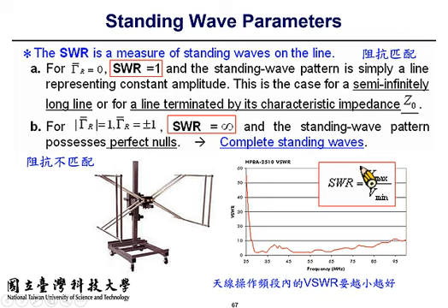We need to pass the so-called EMI/EMC test to ensure that they do not produce noisy electromagnetic waves that interfere with other products, and that the electromagnetic waves produced by other products won't affect the operation of the product to be tested. And to perform the test, it's kind of a broadband test.